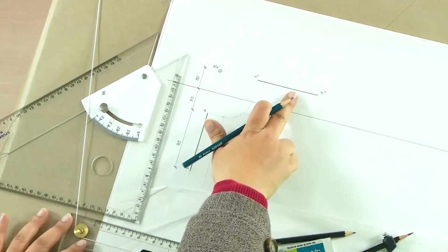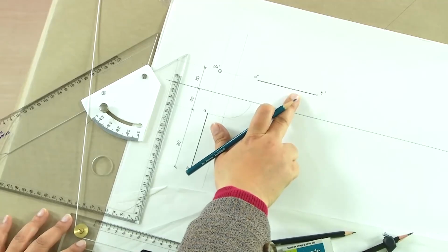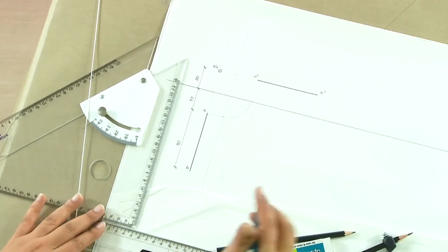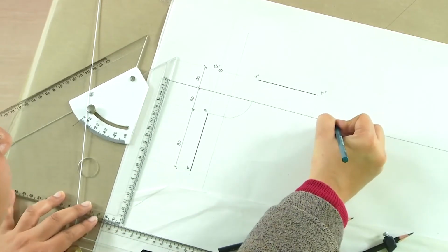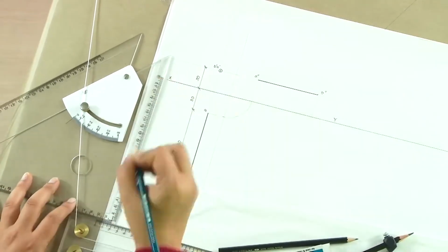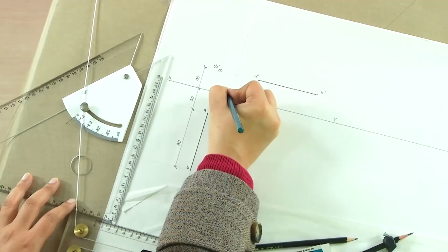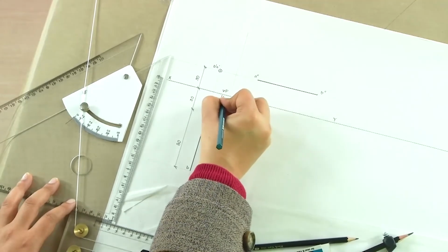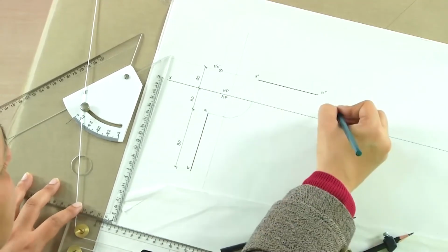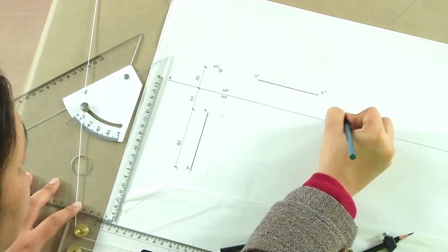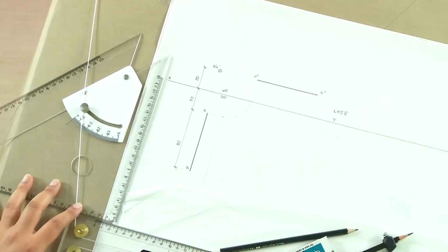And the true length of the line is also seen in side elevation, because when the line is perpendicular to VP, it is also parallel to the side projection screen. So, here we will now mention the reference line, which is X Y here. We have VP here, HP here, and this is the left hand side elevation, LHS elevation.